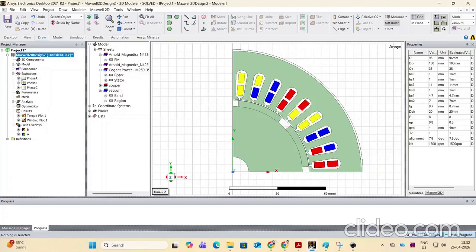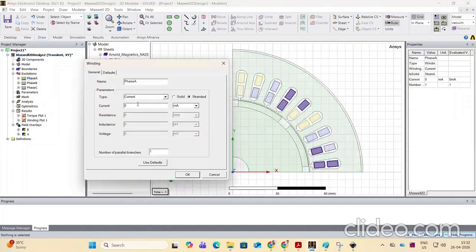Now, in addition to that, in excitation, we have to remember to assign sine excitation. So it should be the RMS value of phase current, suppose it is IPH, multiplied by square root of 2, that means the peak value of current, into sine 2 into pi into F. What is F?